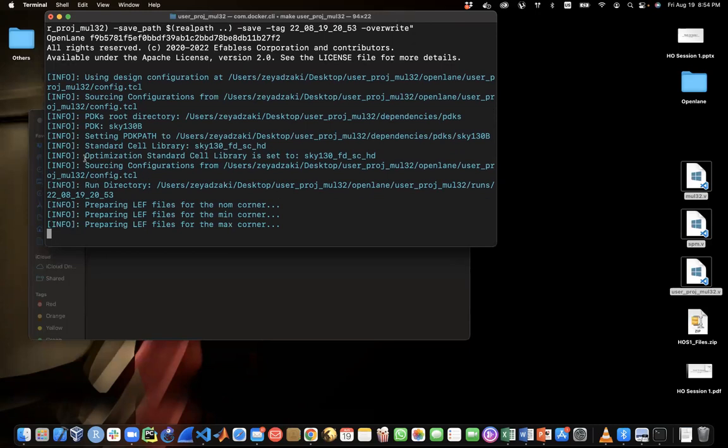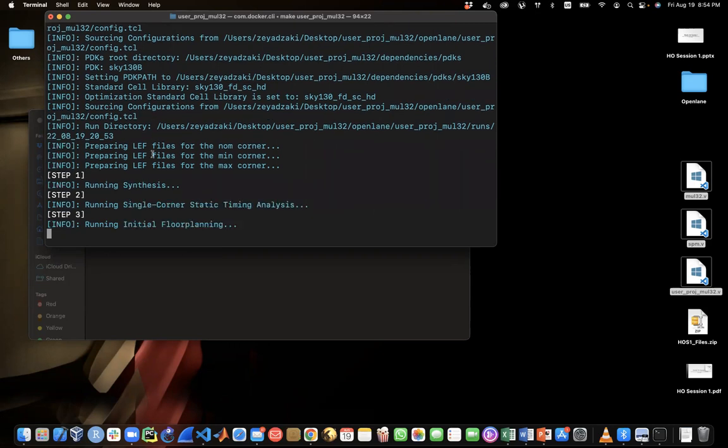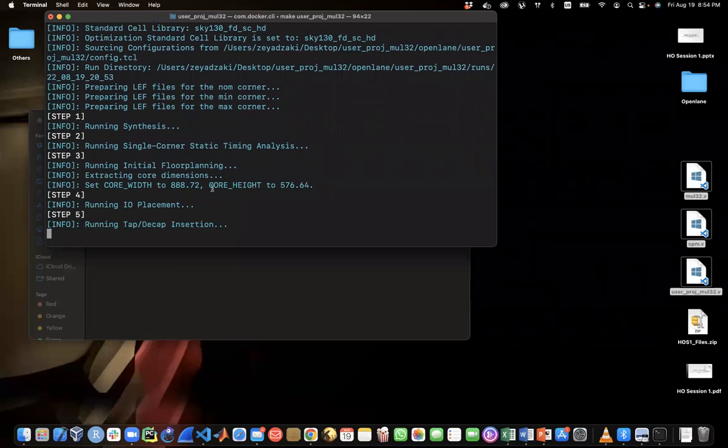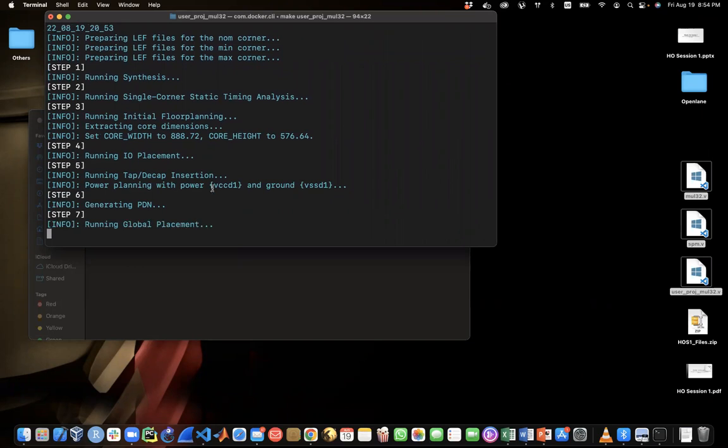A quick note here: if you find that the OpenLane flow logs are different, this means that most probably you are on the older version, so you can recreate your repository, or you can update the Caravel Git branch.